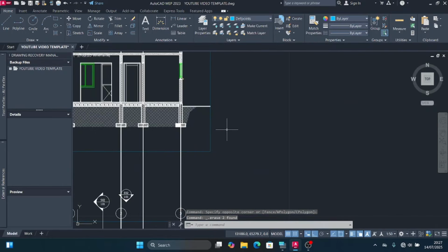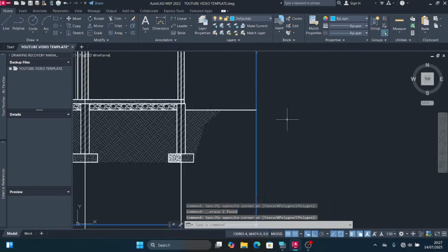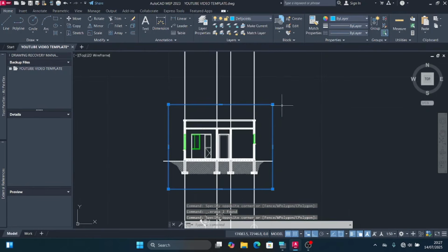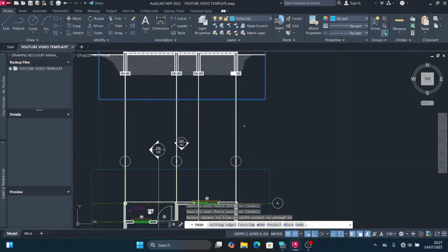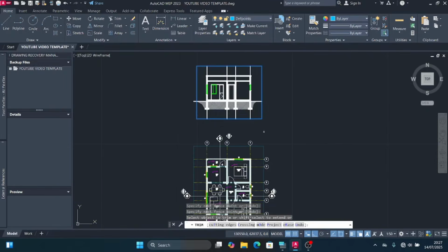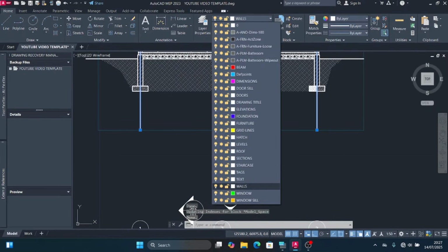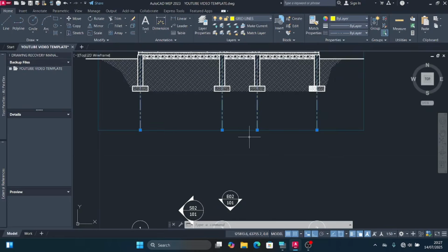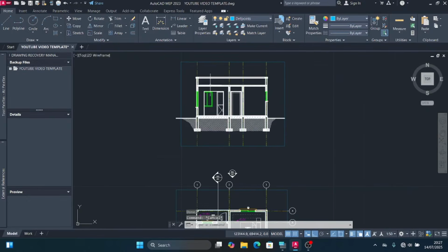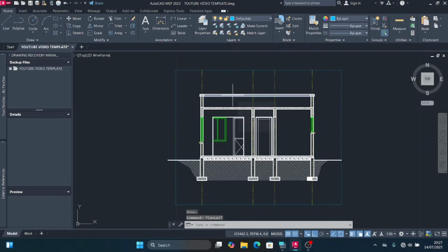Alright. So select this rectangle. Then click at the trim command. Trim off those lines. And also these lines. Press escape. Select these lines. Click at this arrow. Then put them under the layer for grid lines. Alright. Press escape. Then next, I'm going to put the bubbles over here.